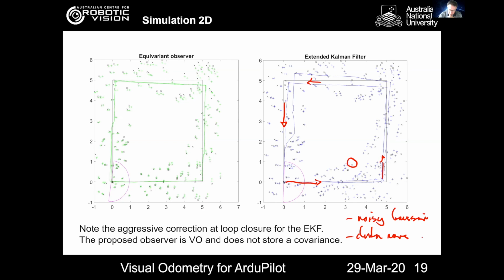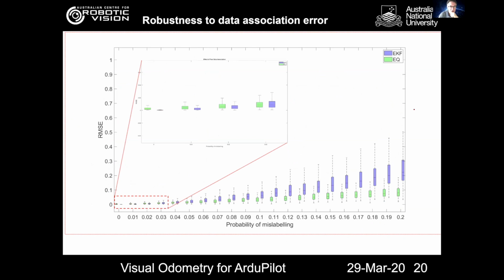What you can see here is a very simple example, a similar principle to the old DCM filter that I derived about 15 years ago. So a very, very simple first order gradient-based observer. And this one here is an optimization-based Kalman filter. What you can see is that by adding in the data association, the Kalman filter is starting to fail. It's because each one of those data association errors is adding non-Gaussian noise, so it's adding something outside of the performance of the Kalman filter.